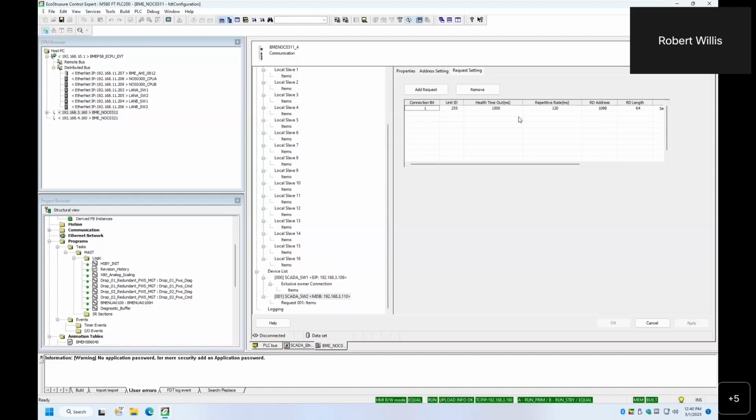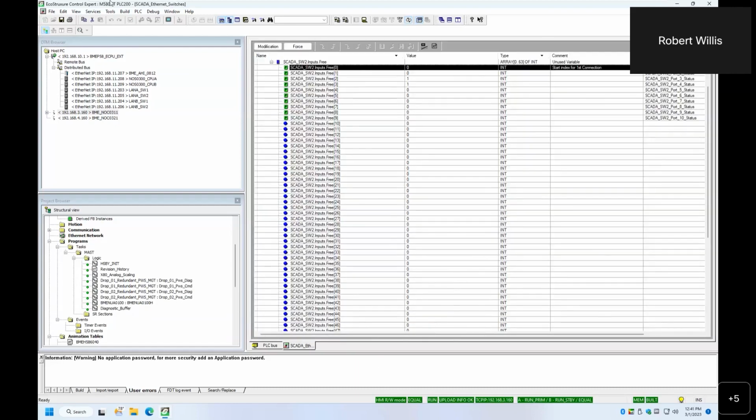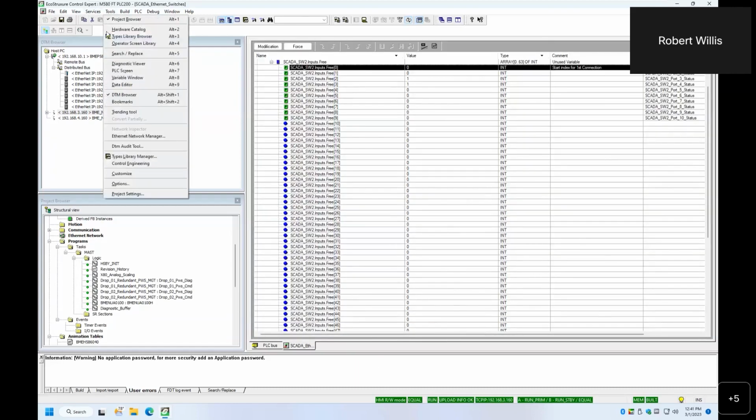Ethernet IP is going to bring in some of that name for you so you don't have to create an alias. What I did in the demo is I created an alias that directly represents that particular word that I'm reading. I could have very well created a DFB to do it. So switching over now, I'm going to show you the Ethernet IP DTM.